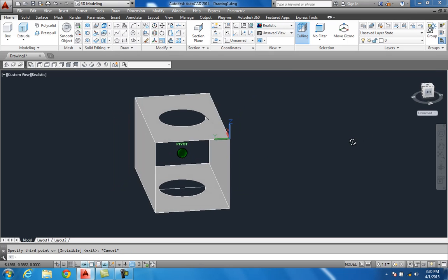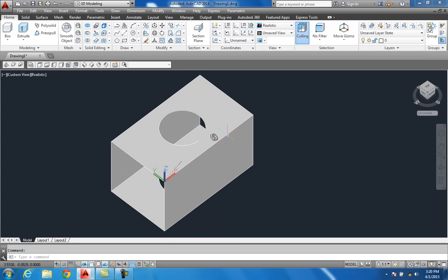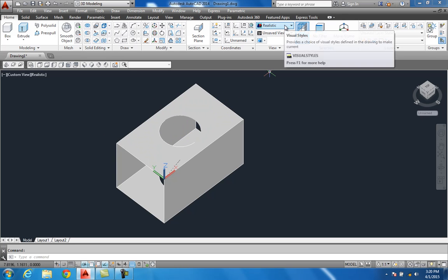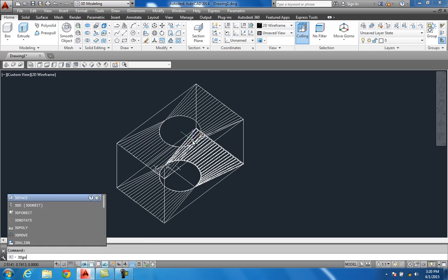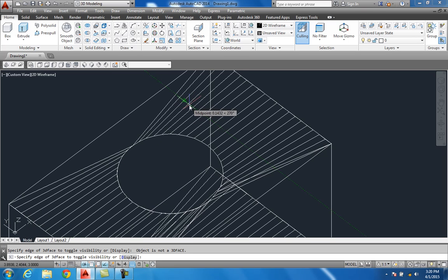So you got all that cleaned up. Now I'm not going to put the ends of that on there until I get this center part done. But there was something I was telling you about. Sometimes they'll have these ugly little lines, and if they show up, you've got to do this. Come in here to 2D wireframe first. See those lines? That's just showing you how that's moving into it. Type in edge, enter. And all you have to do is come in here and click on them.